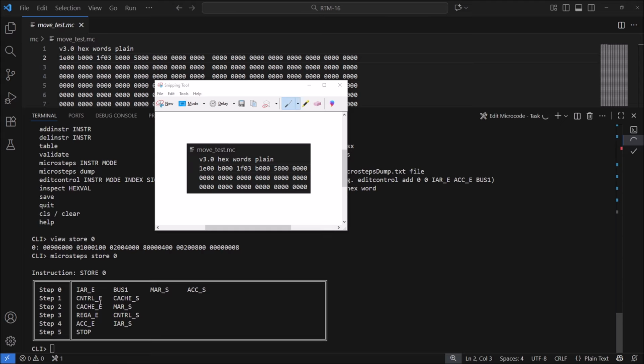Now what we've got up here as well, as you notice, is this bus 1, because when we're finished with this command, an instruction, we don't want to be sitting in this position, because this position here contains a memory location. It doesn't contain the next instruction. The next instruction is the next one along. So we're going to have to add 1 on to our instruction address register. That's why we've got this bus 1 and the accumulator set, because it's now going to take in the accumulator, and the accumulator will be pointing to this next address here.